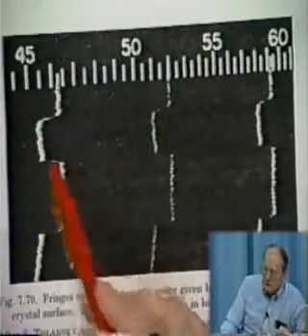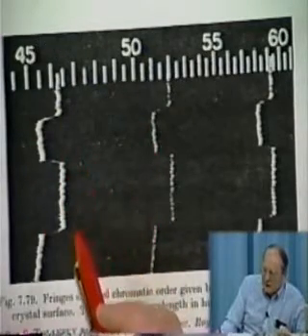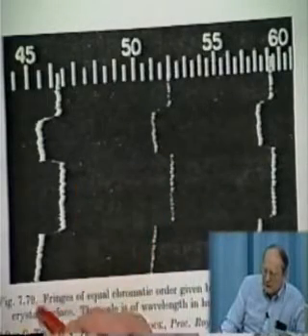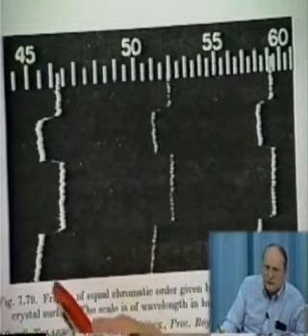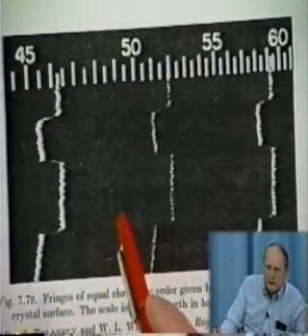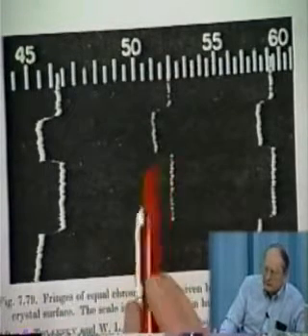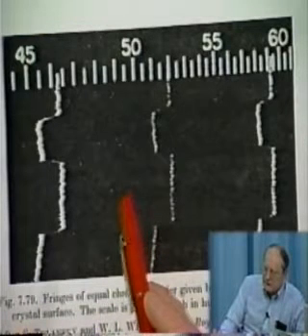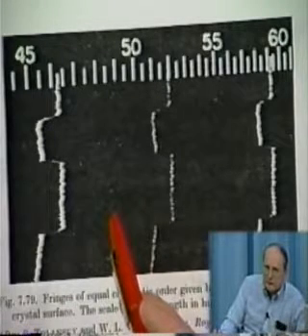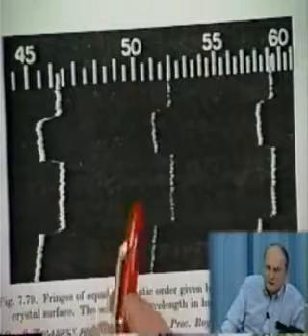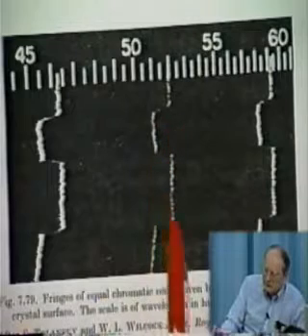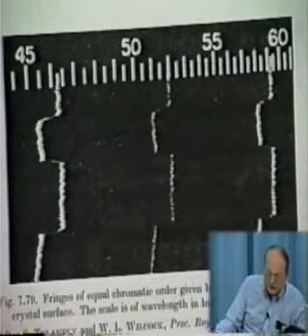And that is a tricky question. In these instruments, you always have a reference surface, and so some way you have to certify that reference surface. And so you probably want to compare that with several other surfaces. And again, I'll put in an ad for 513 next semester. We do talk a little bit about absolute measurements of surfaces. But that's a tricky thing. How do you know how good your reference is? But probably comparing several surfaces, bootstrapping your way up, is an approach. So that's true, we're only measuring the difference between the two surfaces. Any other questions on this?